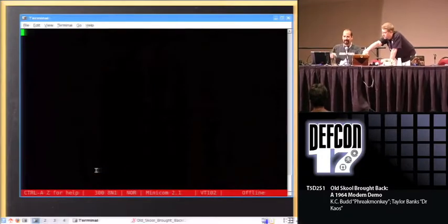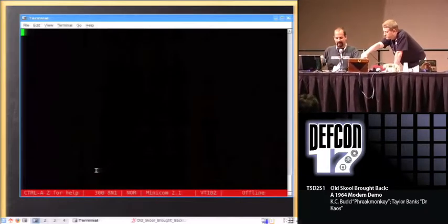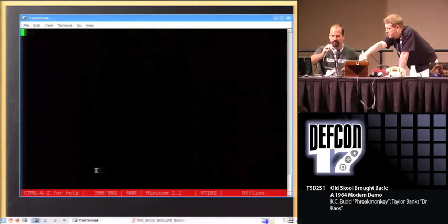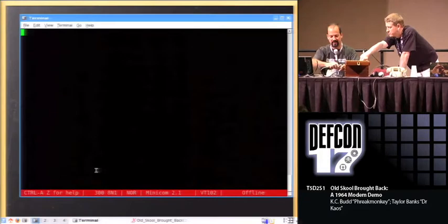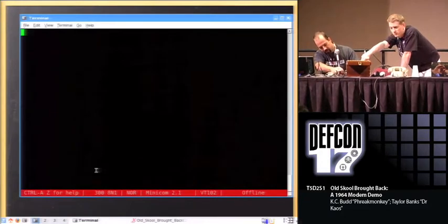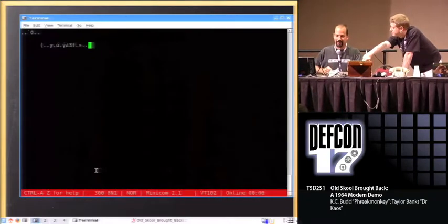So it's putting out a tone. It's not waiting for any commands or anything. Like I said, it's just an analog oscillator device. And what's interesting is since it's not receiving the plus 12 volts, it's actually putting out the space tone. It's not putting out the mark tone, which makes it mark idle. When it receives 12 volts from the serial port, it puts out the space tone.